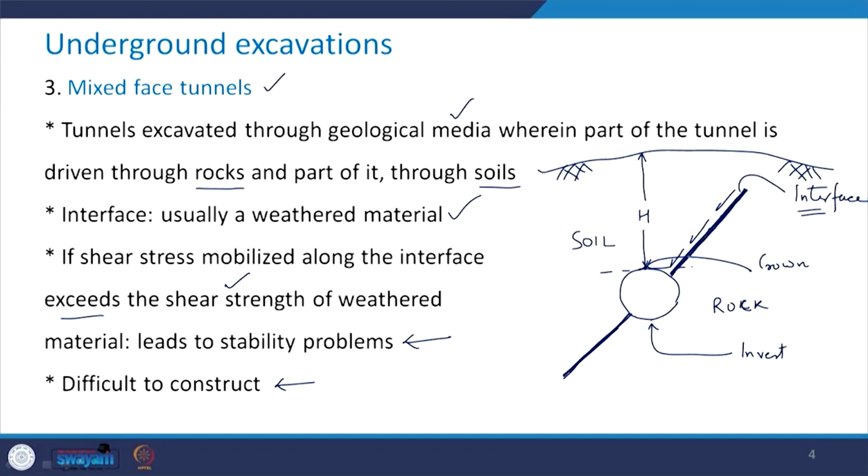The interface is a weathered material, and whatever shear stress is mobilized all along the interface, if this exceeds the shear strength of this weathered material, then this leads to a stability problem. So, this is a difficult situation as far as the construction is concerned.